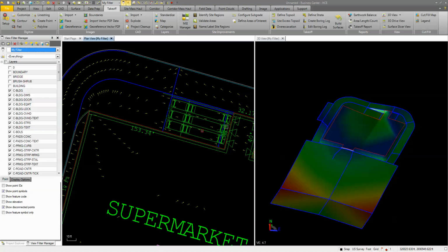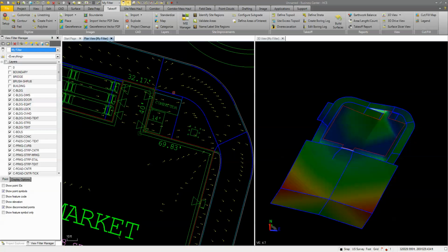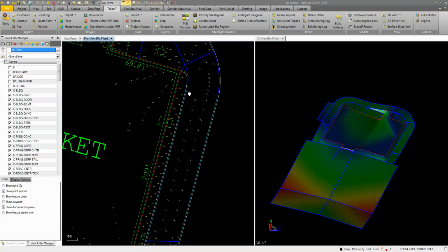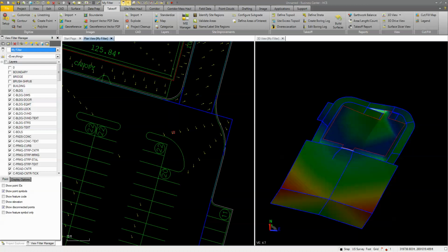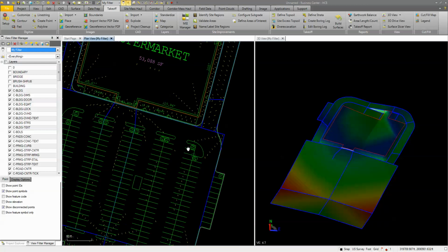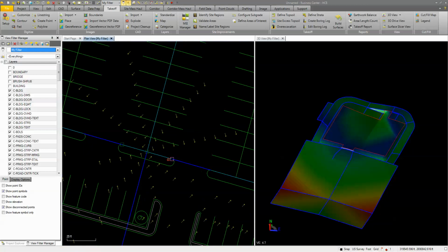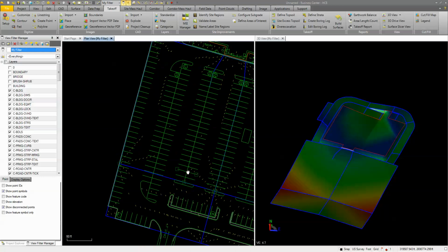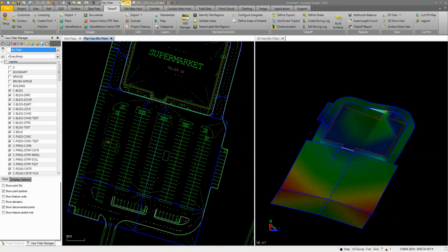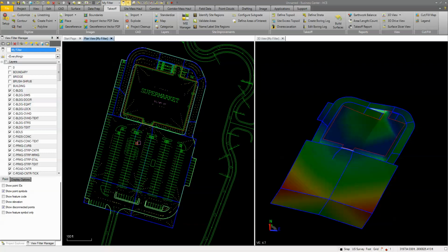It's going down into our trench drain. As we work our way around, we're grading over to this area, which is all draining out, all sloping this way, down into our low spots. Same thing here, we're sloping that way. So with the slope arrows, we're able to see where we're tying into, what we're sloping into, and everything looks pretty good for what we call our general planes. So what we'll do in the next video is show you how we'll grade this out, we'll check some adjustments over here, that should be fine, and we'll fix the building.